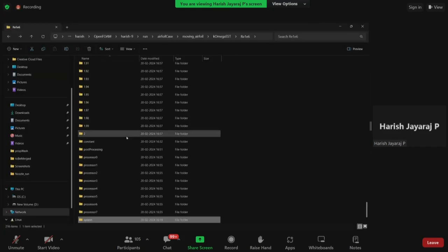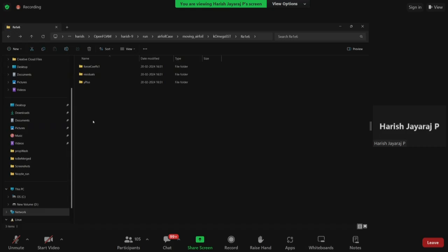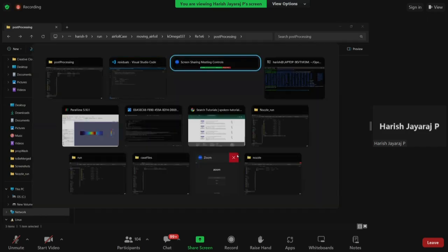The method is, after you run the simulation, you will find a new folder which you did not create called the postProcessing. So only inside this we found the force coefficients. Inside that we found the coefficients.dat, which we used to plot to see the CD CL graph, right? So similarly, we will be using foamMonitor command or GNUplot command to view it.